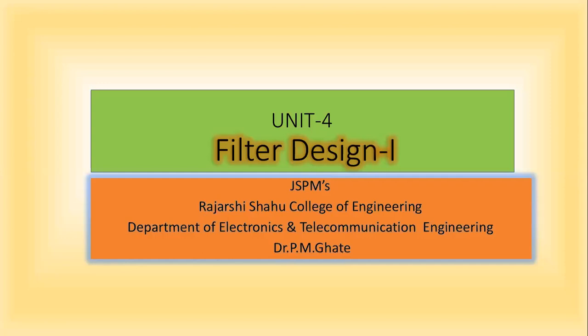Now, when we look toward the designing of filters, there are different methods of designing a filter. In both categories, filter designing is a very important aspect when you want to design a filter as per the customer need. We have different methods related to the IIR filter. The first method of designing an IIR filter in the digital domain is approximation of derivative. The second method is the impulse invariance method. The third one is bilinear transformation.